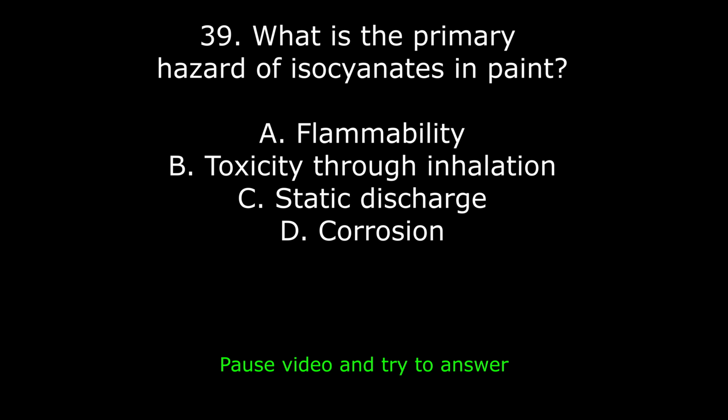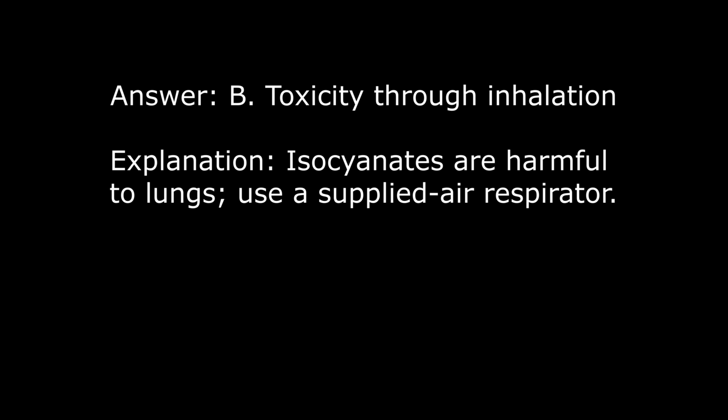39. What is the primary hazard of isocyanates in paint? A. Flammability. B. Toxicity through inhalation. C. Static discharge. D. Corrosion. Answer B. Toxicity through inhalation. Explanation. Isocyanates are harmful to lungs. Use a supplied air respirator.